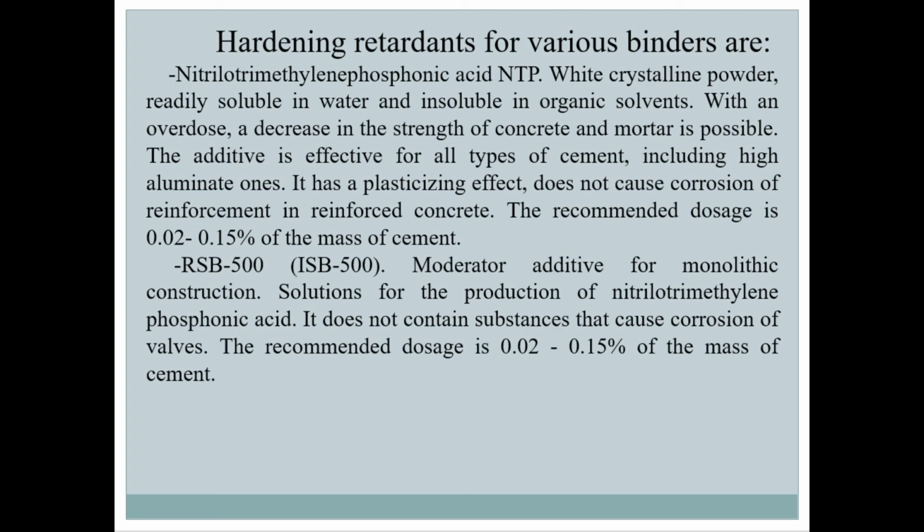With an overdose, a decrease in the strength of concrete and mortar is possible. The additive is effective for all types of cement, including high aluminate ones. It has a plasticizing effect and does not cause corrosion of reinforcement in reinforced concrete. The recommended dosage is 0.02 to 0.15% of the mass of cement.